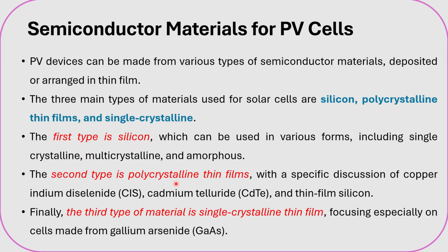Thin film cells are deposited in very thin consecutive layers of atoms, molecules, or ions. They have many advantages over their thick film counterparts. For example, they use much less material. The cell's active area is usually only 1 to 10 micrometers thick, whereas thick films are typically 100 to 300 micrometers thick. Thin film cells can usually be manufactured in a large area process, which can be an automated continuous production process. Finally, they can be deposited on flexible substrate materials also.